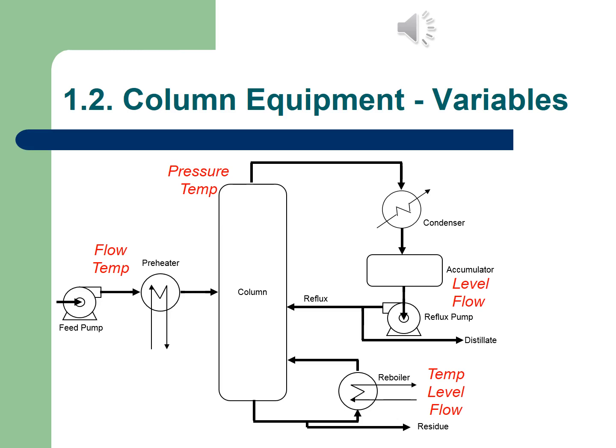Yes, and then of course the level there will decide how much you actually want to let go off as a residue. And temperature will have a great effect on the bottom product, this reboiler heat exchanger, eventually to determine what is the temperature of the column.